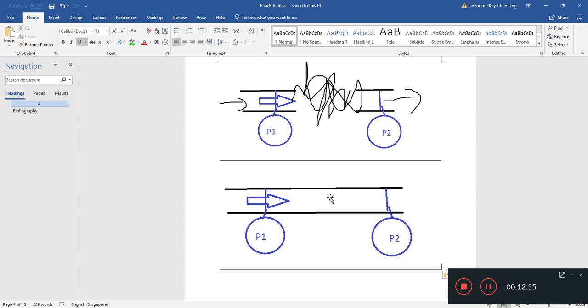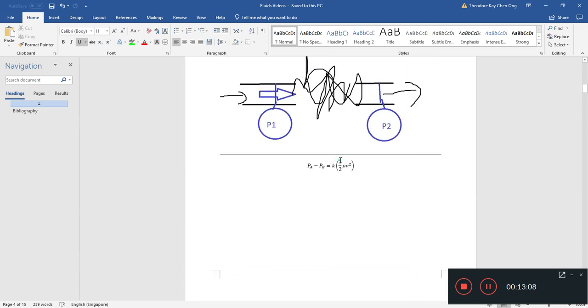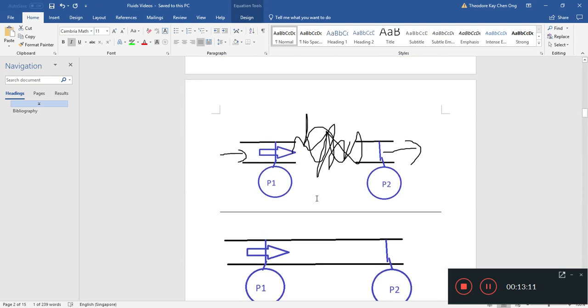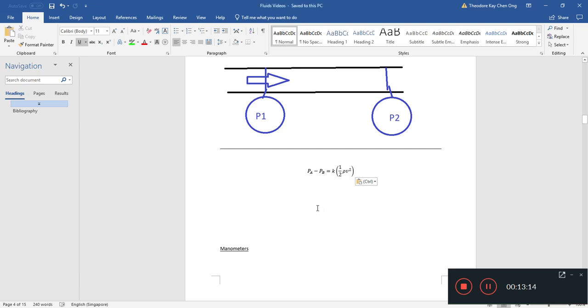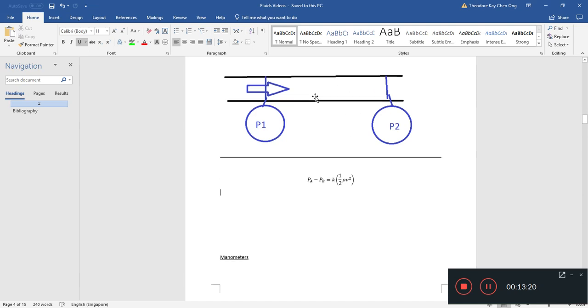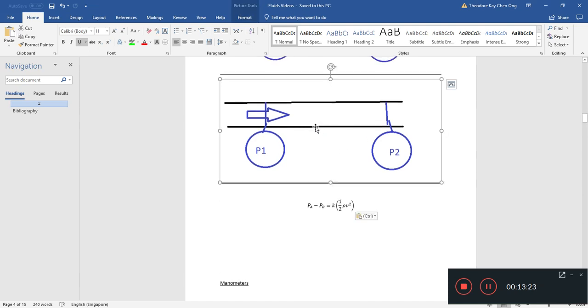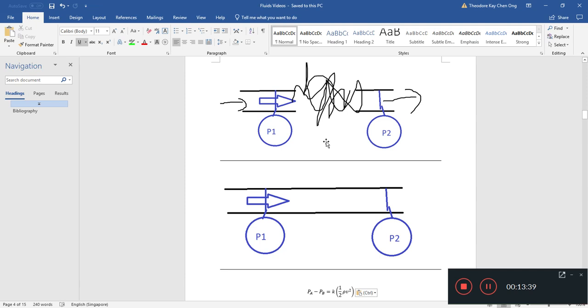Now, how are we going to find these K values and estimate the frictional losses before we build the actual thing? These are some of the things that engineers need to think about. That's why finding these K values isn't always as simple as this, because there are practical difficulties in building this test apparatus, especially if this pipe was 1,000 kilometers long, or you have a complex piping system with many valves. So we have to find a systematic way to estimate what the K values are.